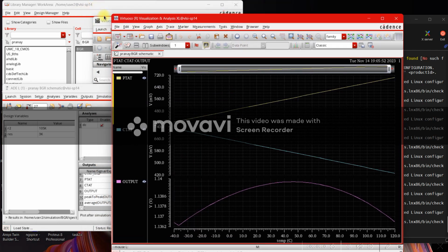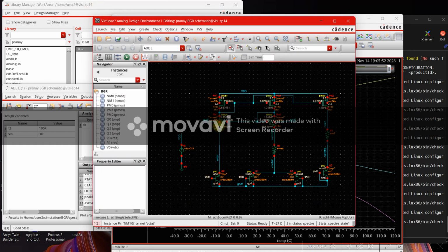So we used a current mirror to maintain these two voltages at the same level. Then I've used another current mirror branch to get the VREF by keeping two voltage sources in series. This will give you a CTAT voltage from ground to this point, and across the resistor, since the current through the resistor is PTAT, the voltage drop across the resistor is also PTAT. The slope of the PTAT curve can be controlled by this resistor and the number of diode-connected BJTs in this branch.